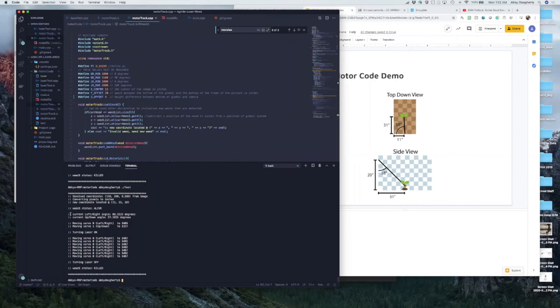And then here you can see that the angles have been calculated, which match the image to the right on the PowerPoint slide. You can see 58 degrees and 88 degrees, just to help visualize. After the degrees are calculated, we move the servos to those locations, and then the laser is turned on. And then next, we're moving the servos back and forth. It iterates a few times across the stem of the weed, 1 degree to the left and right. After it has fired, the laser is turned off, and the new weed status is reported, which is killed.